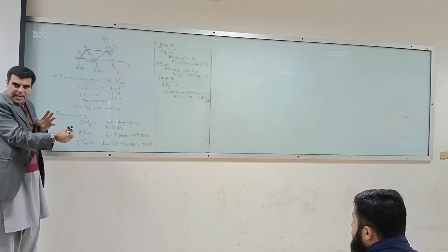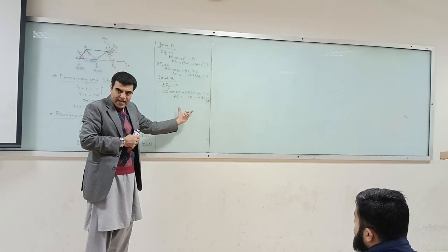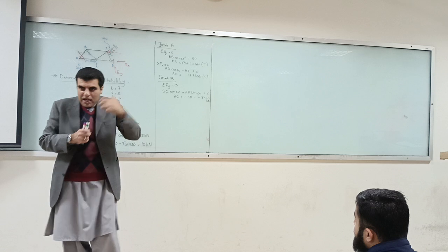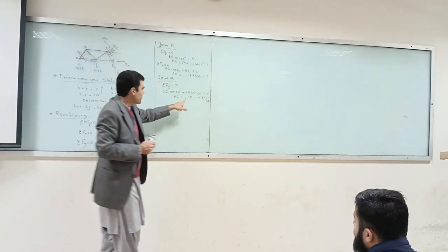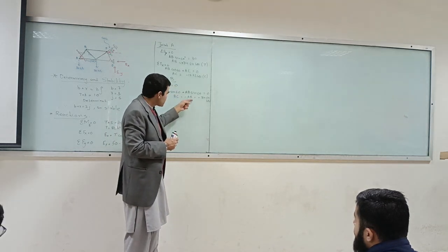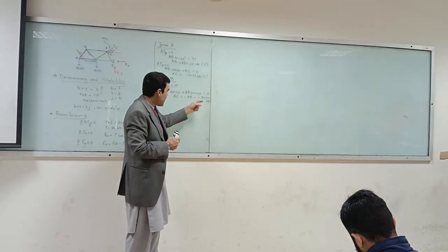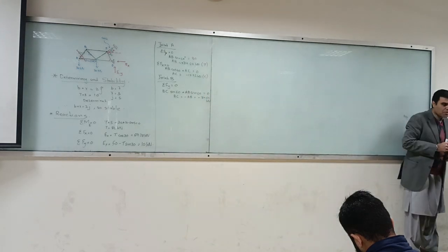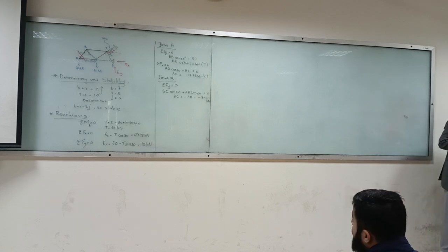After writing my equation, once I work it out and come to the form where I have to plug in values, then I use the actual values which I have calculated. I got from my equation BC is equal to minus AB. Now in this AB, I put the actual value which is plus 34.64, and I get minus 34.64. So you can do it anyway, but the important thing is that you stick to that convention.